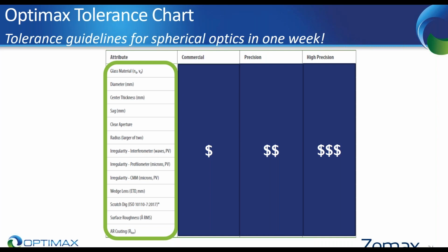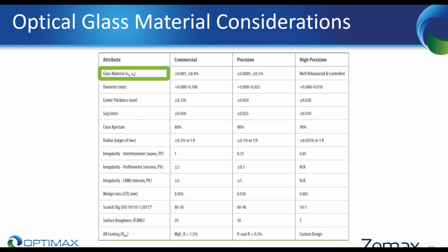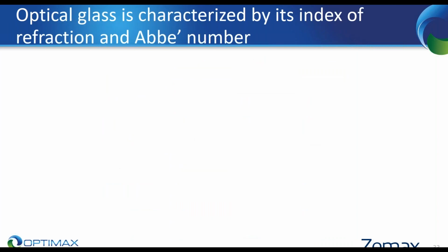And so as you're tolerancing your next design, if you have the option to loosen one of those tolerances, it might help save some time. The other recommendation I will give over and over again: as soon as you have a design that you want to have fabricated, instead of shooting it over the bow, make sure you have a conversation with your manufacturer about what we can possibly do to reduce some of the cost here. There may be some good suggestions that result.